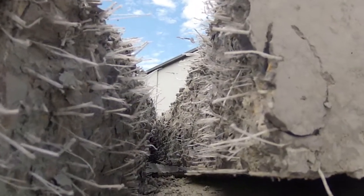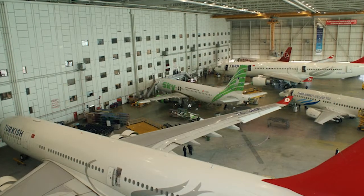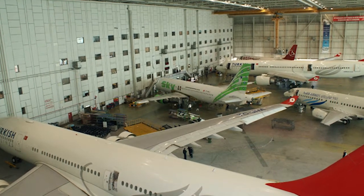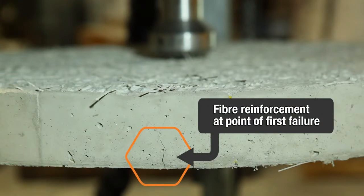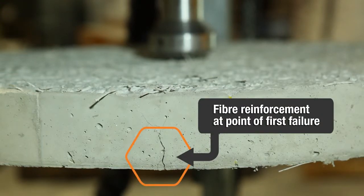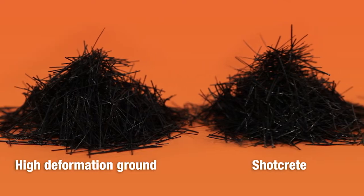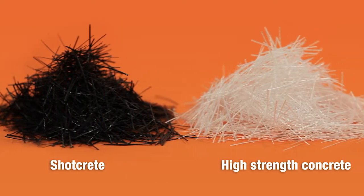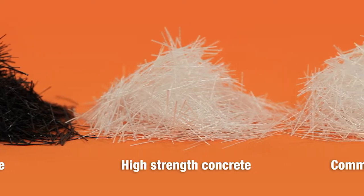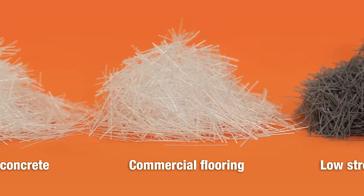Because EPC's bar chip fibers are homogeneously mixed through the concrete, when concrete is under stress through ground deformation, movements or loading, the fibers begin reinforcing at the exact point of concrete failure, significantly reducing the risk of crack propagation. When specifying fibers, it's important to understand that fibers available in the market today vary greatly in design, resulting in different classes of fiber for different applications.